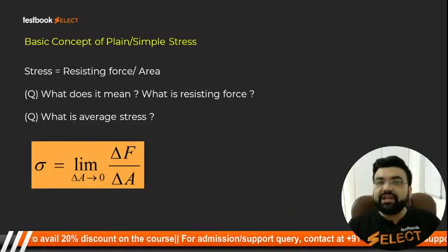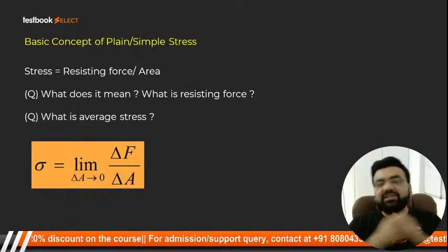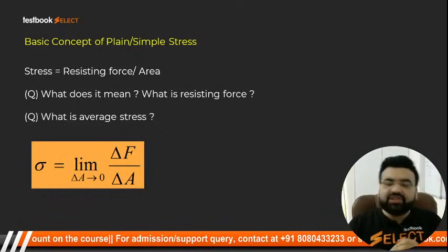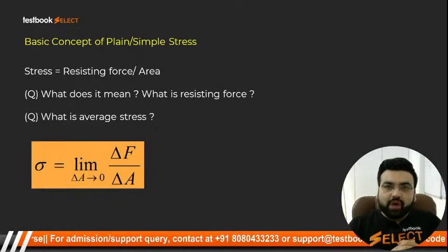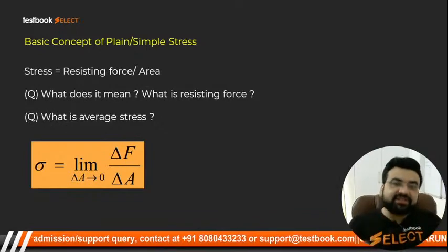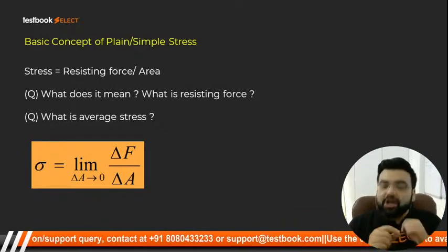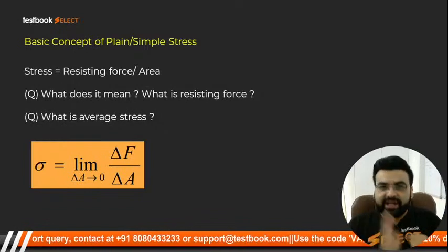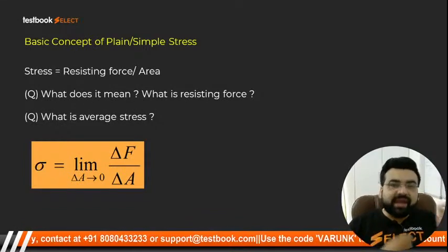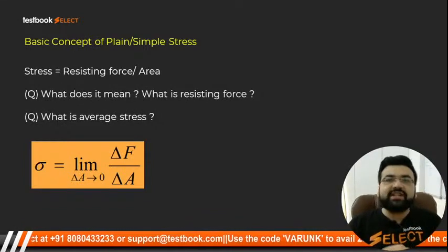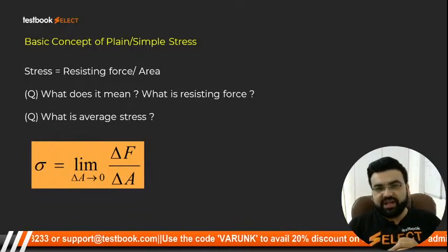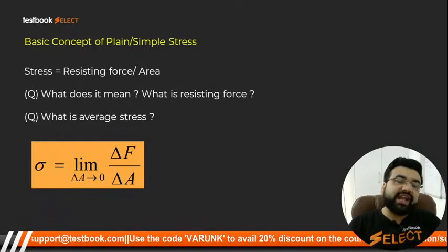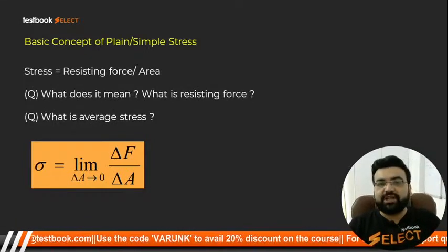Now students, what is the meaning of this stress? Let us understand it. So stress is just the resisting force per unit area. It is very important to remember it. It is a resisting force per unit area, not the applied force per unit area. That is a very big misconception which the students have in their mind, that the stress is the applied force per unit area. It is not the applied force per unit area, it is the resisting force per unit area.